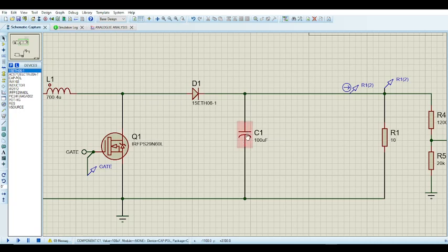So you want to use a capacitor like this, which is electrolytic, and you want to use non-electrolytics in parallel with it, because it helps a lot with the parasitic resistance issue, and it gives you a much smoother voltage on the output, a lot smoother if you use them together.